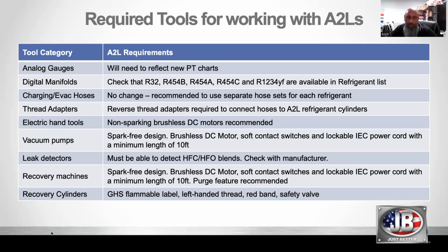Vacuum pumps we spoke about. Try and go for a spark-free design, something that is A2L compatible. I'll run you through a couple of slides of some of the products that JB has, but we do have a newly designed A2L pump, which has a brushless DC motor. And we also have an AC motor pump, which is an actual spark-proof design. So that means it's got a sealed capacitive unit, and it's actually rated to A3, and that's been through UL testing as well. So that's used in higher volatility applications.